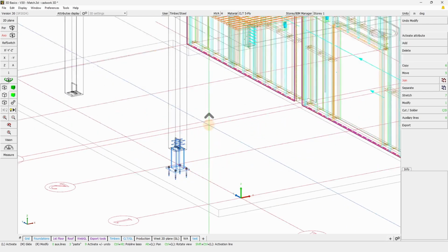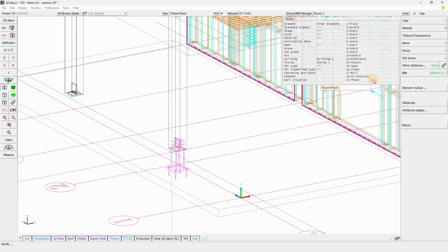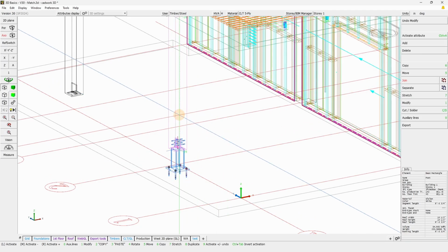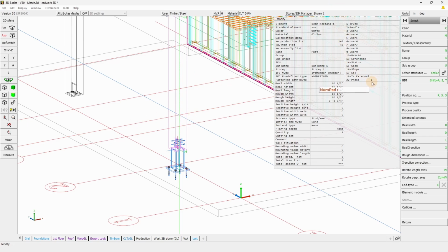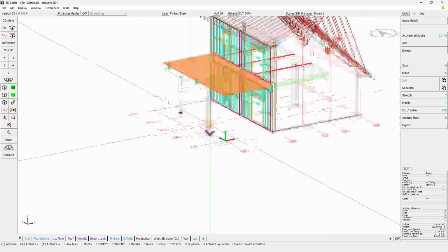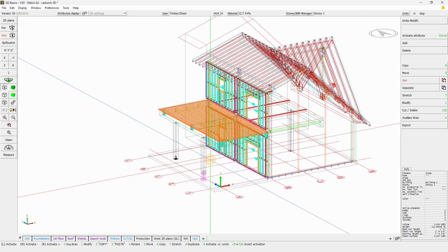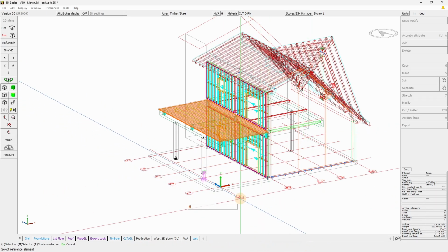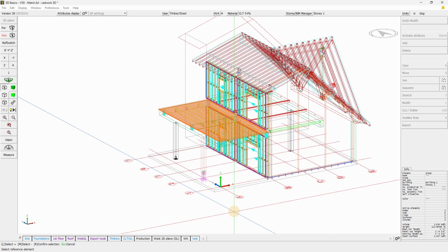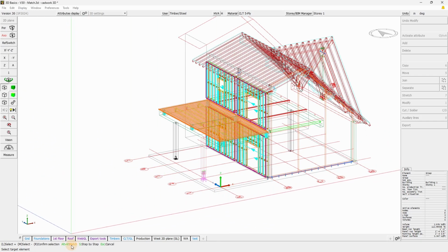So here currently, the element that I wish to copy belongs to phase 1, as is the reference. So if we select this element and wish to copy it on all these 6 posts that belong to different phases, I copy with 6 and H for reference, selecting the reference, right-clicking to confirm, and here you will see that the match can be activated or not using Alt-V.